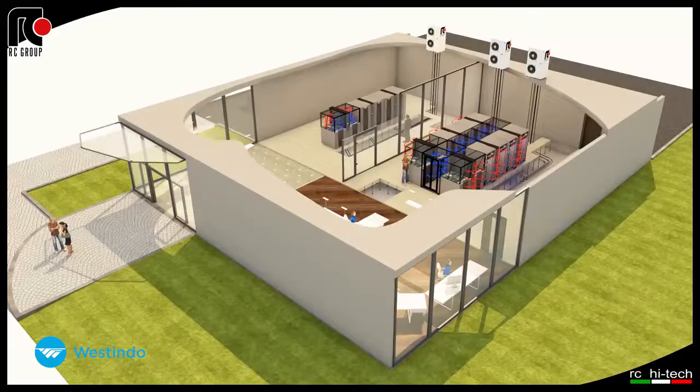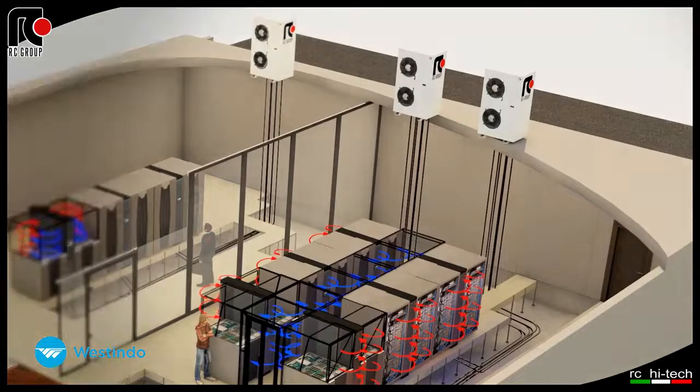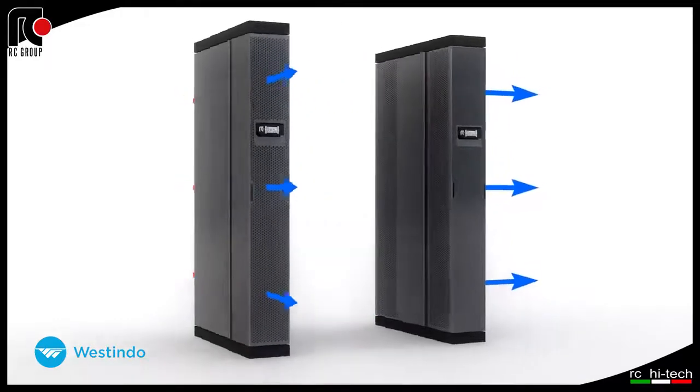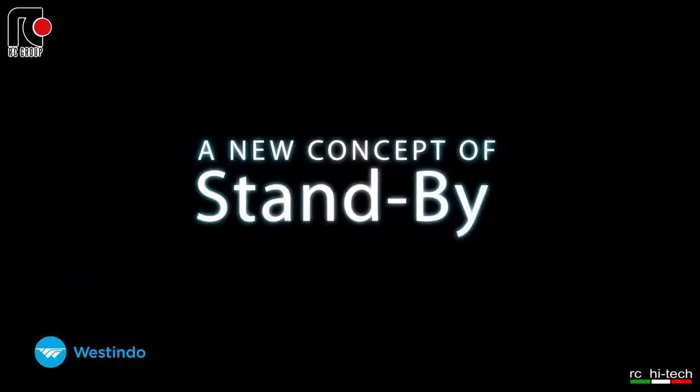Up to 3 indoor evaporator units can be matched to each single outdoor motocondensing unit, being complete with EC motor-type axial fans, inverter-driven scroll compressor, and aluminium-aluminium microchannel type condensing coils. The cool-side indoor units are also available in a chilled water version for combining with one of the many types of RC Group liquid chiller options, a new concept of standby.